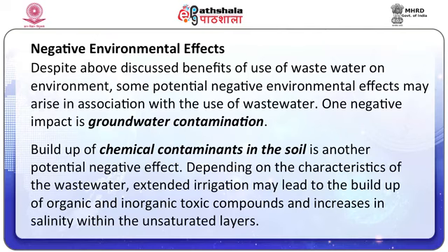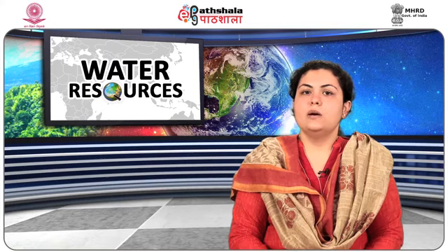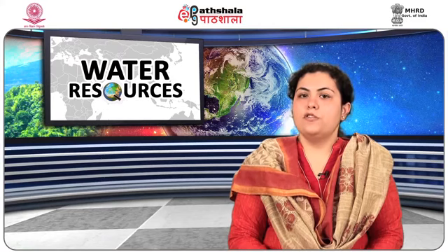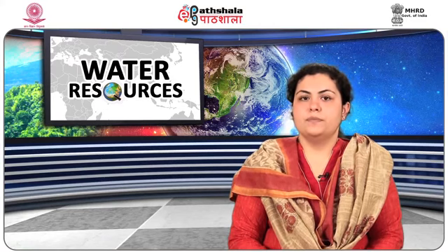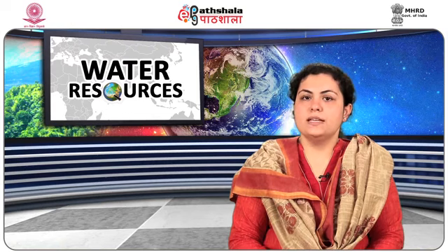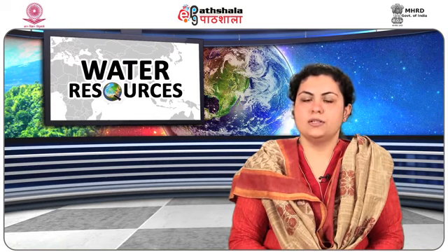Buildup of chemical contaminants in the soil is another potential negative effect. Depending on the characteristics of the wastewater, extended irrigation may lead to the buildup of organic and inorganic toxic compounds and increases in salinity within the unsaturated layer. To avoid this possibility, irrigation should only use wastewater of predominantly domestic origin. Adequate soil drainage is also of fundamental importance in minimizing soil salinization.